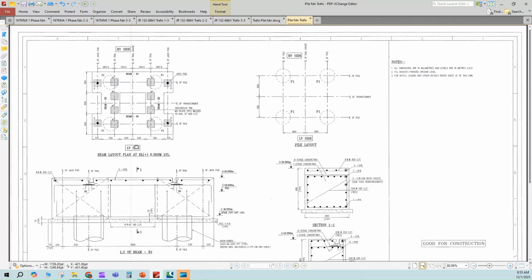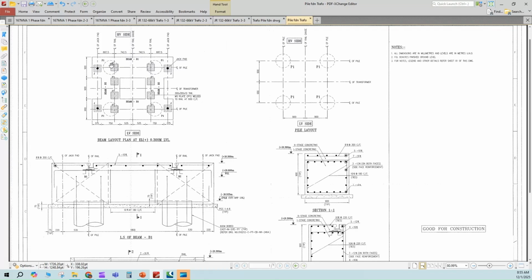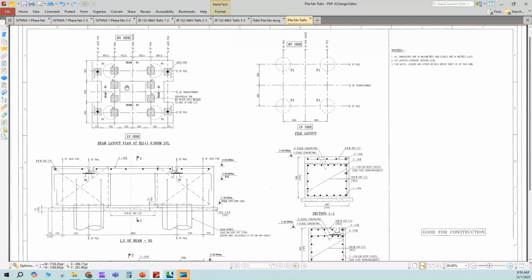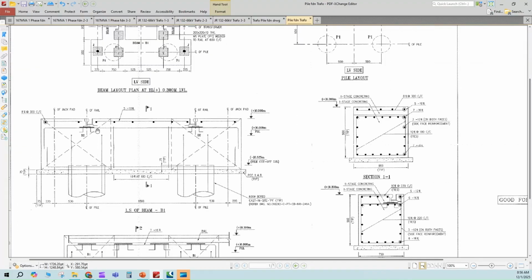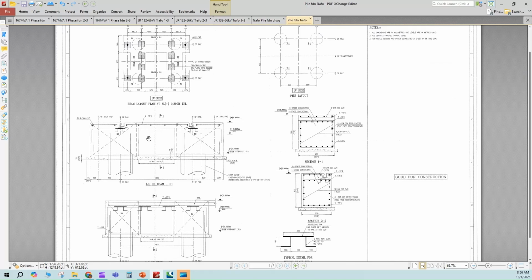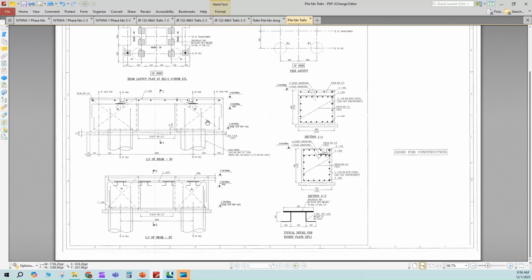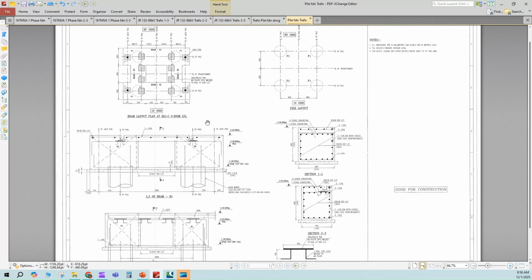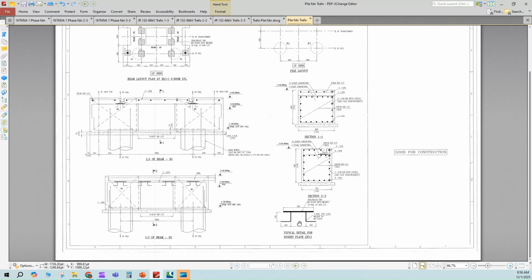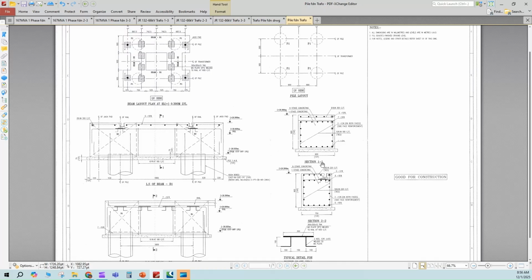So this is the HV side and LV side, which has 4 piles. These are the inserts. This hatched portion is the insert plate where the transformer is going to rest, and these are the rails. This is a 110 kV/33 kV transformer foundation, which is for a 16 MVA transformer. These are other details of inserts and the pile cap details. Pile cap is 900 mm deep.